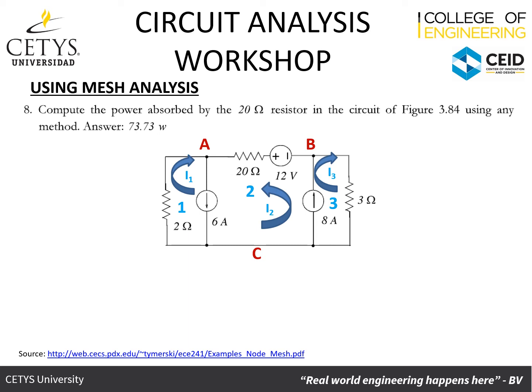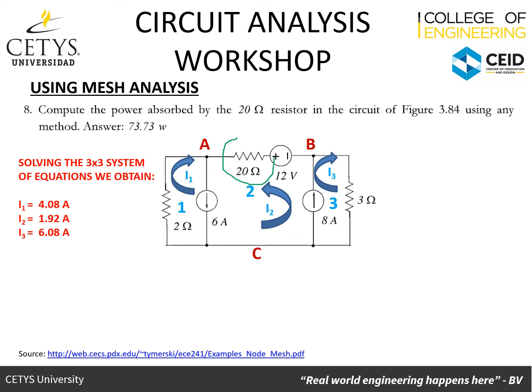So now that we've got the three equations and we've solved them however way we want to solve them, but we could have used the web page that I provided, we're going to find the three currents, I1, I2, and I3, which the values you can see there. Now, remember that what we're looking for is the power that's dissipated or absorbed in the 20 ohm resistor, okay? So really we don't need to solve everything for the circuit. We just need the values that are going to give us enough information to calculate that power.